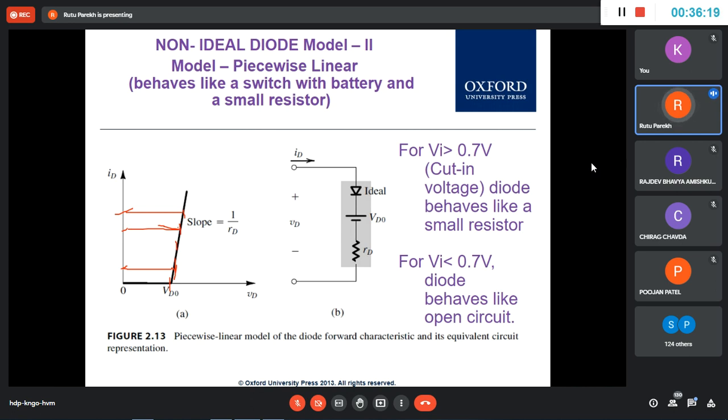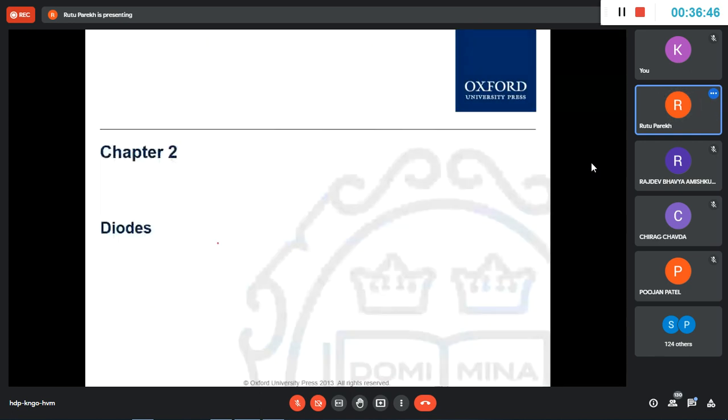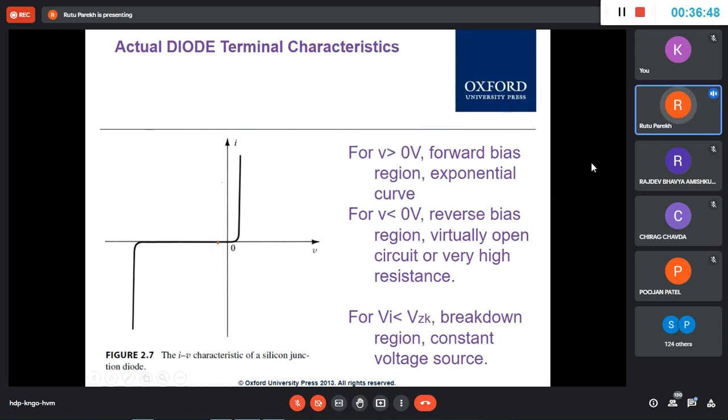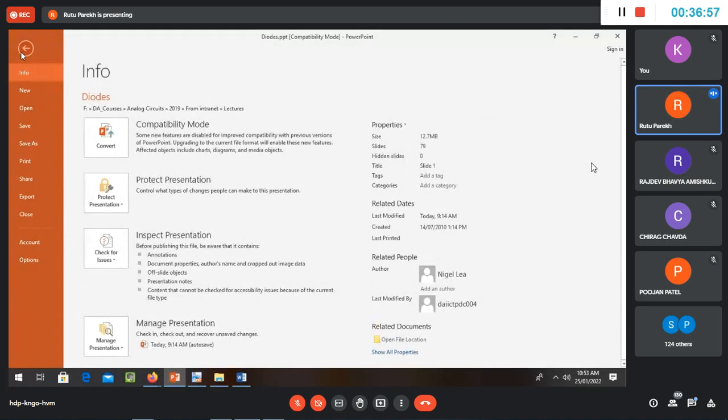We saw that when you have a resistor or a capacitor, those components, the value remains same. Even if you change the voltage, if you give a resistor whatever voltage, it will remain R only. But here with the change in voltage, although little change, okay, there is a change in R. And why is that happening? Anybody would like to help me? Why is that happening? Physics, if you go to the physics. Because the depletion region is decreasing. Very good, very good. This is what I was expecting.